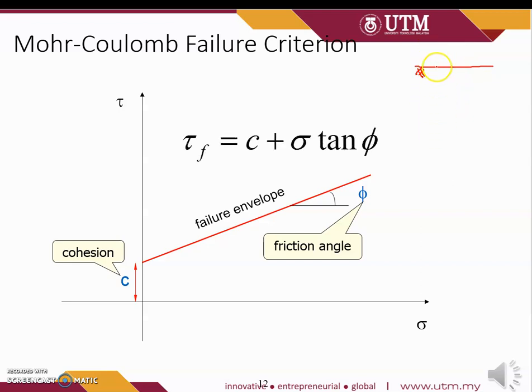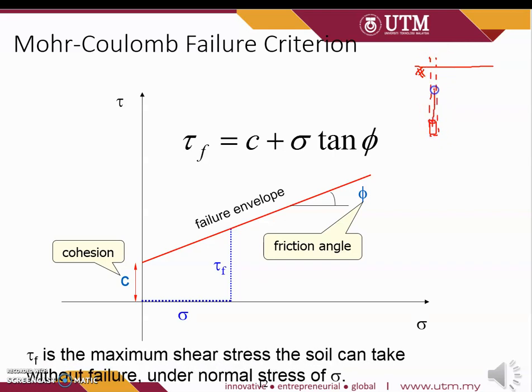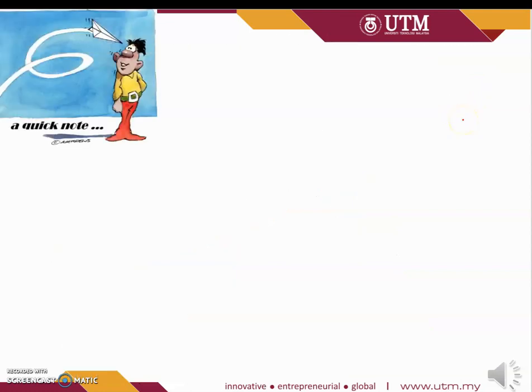bore log activity. We will make some wells, take soil samples and bring them outside to the lab, and we can prepare the data. We can plot the tau and also the normal stress of the soil, as long as we know the unit weight, C, phi, and so on.